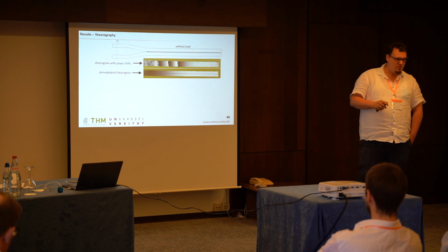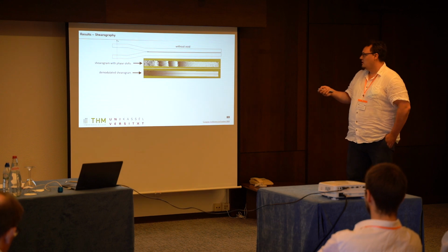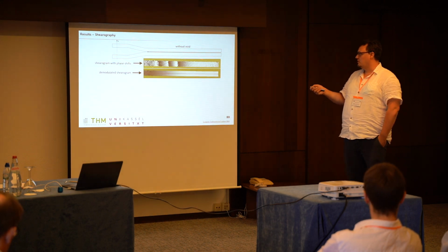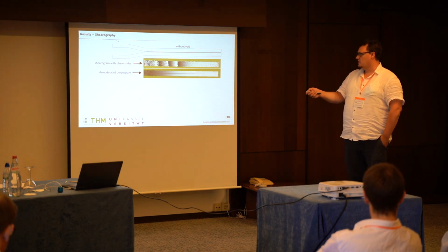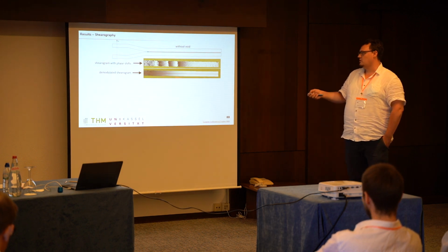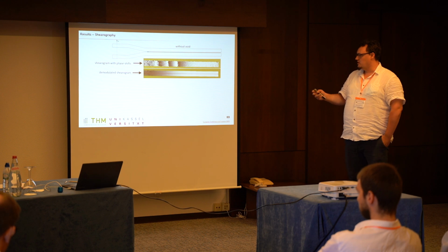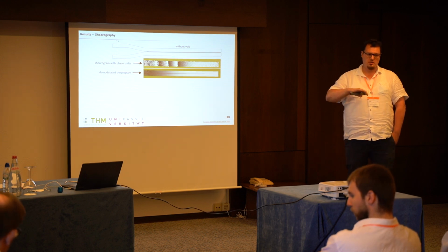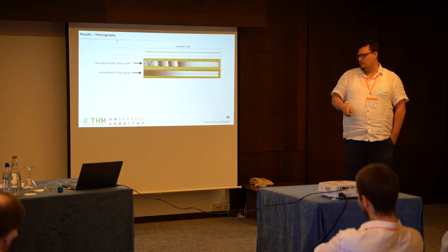Now results of the shearography measurement. On the top you see for the specimen without void the shearogram with these phase shifts, and below the demodulated shearogram, and you see it's very smooth and is like we expected from the deflection curve.